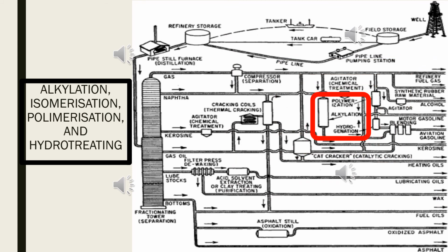If you want to increase the octane value of aviation fuel, you can react gases like isobutane and isobutene, using the alkylation process at between 273 and 303 Kelvin. Remember to supply cooling as the reaction is exothermic.